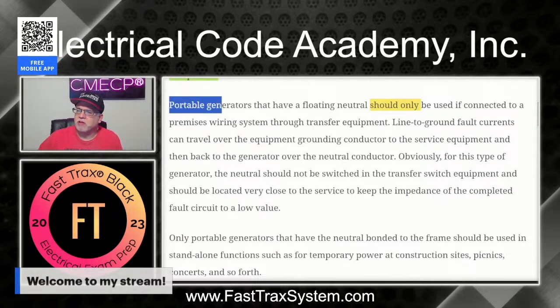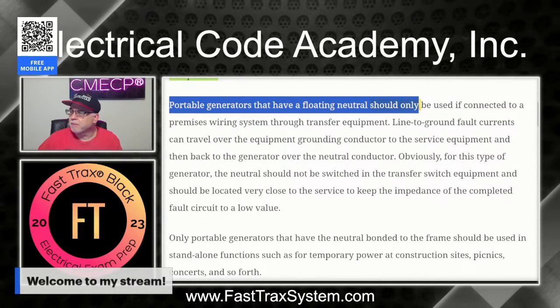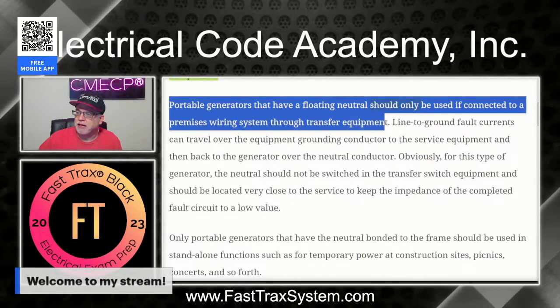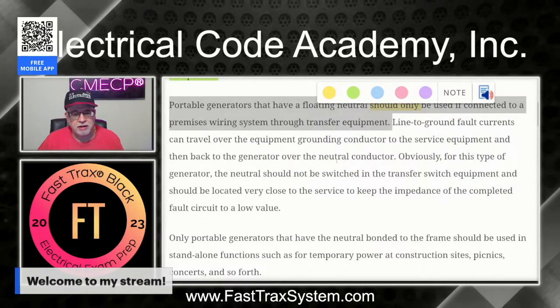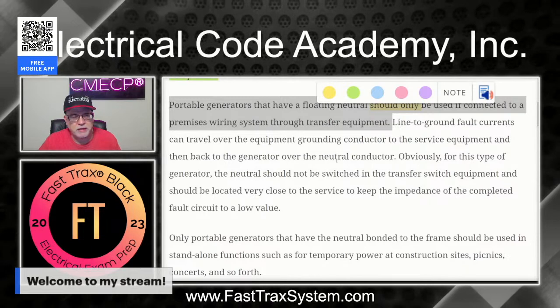Next, portable generators with the floating neutral should only be used if connected to a premise wiring system through transfer equipment. Okay, so if you have a generator and it is a floating neutral type generator, then you should make that application through a transfer switch.